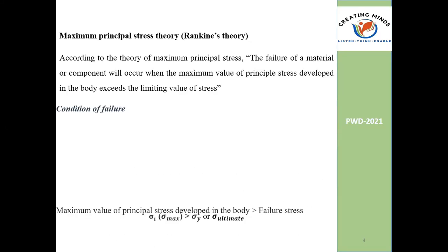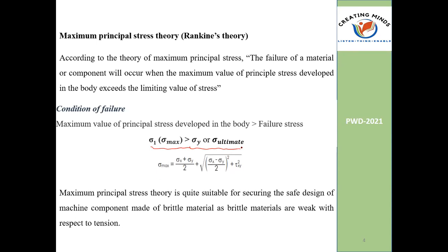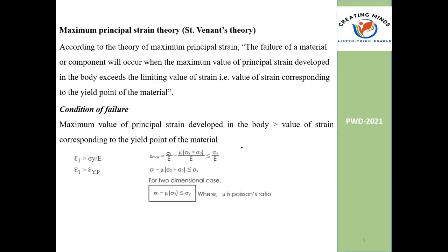These are very important. Mainly, what you have to remember while concentrating on failure theories are the conditions. The conditions play a major role when you are solving numericals, and you may expect a few theoretical questions, especially on the yield locus. The yield locus for principal stress is a rectangle. What is the yield locus for the principal strain theory? Yesterday in class we discussed it. Parallelogram.